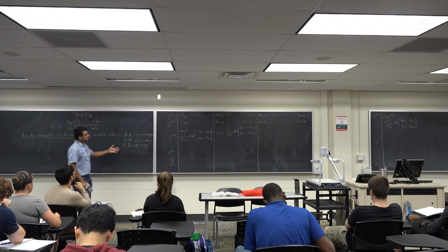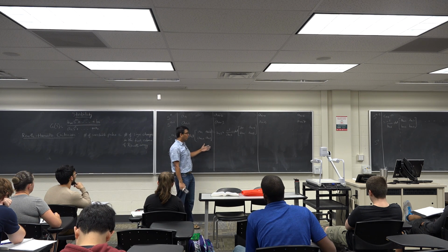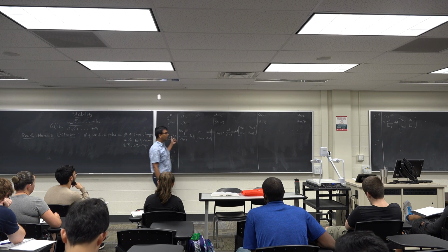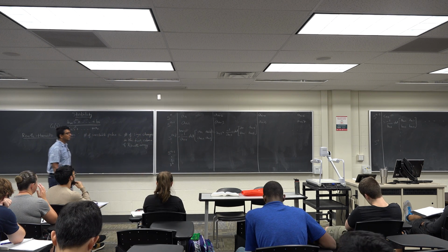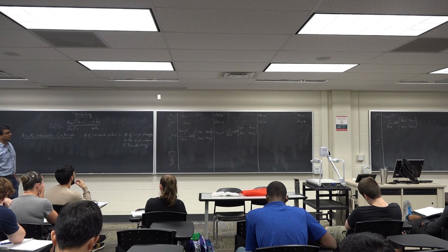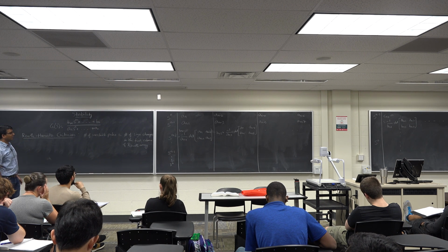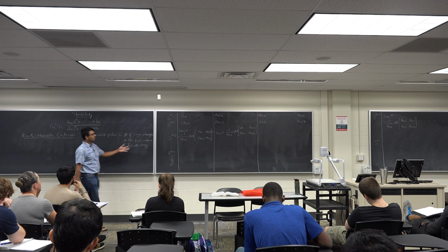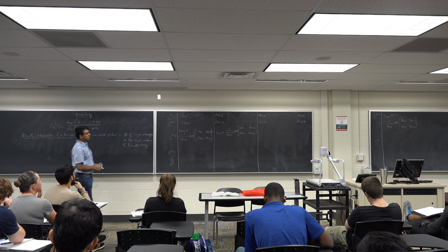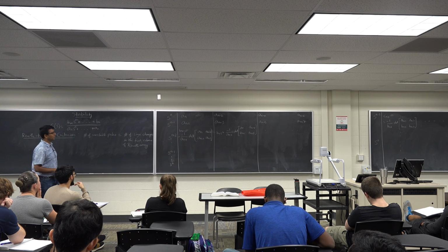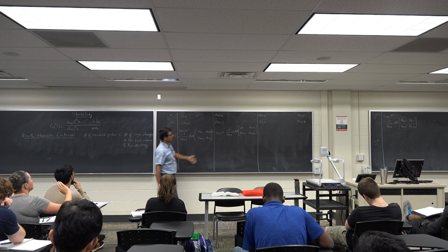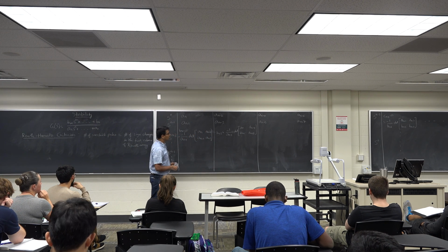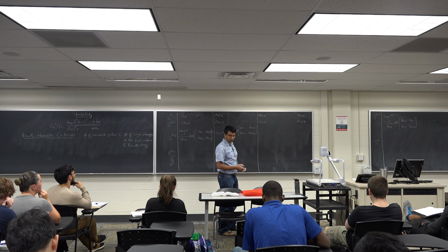So constructing this array is not a problematic affair even in the 1870s. If you know the system's transfer function, you can construct this table. It's still a laborious task, but it can be done by hand. And you can ascertain how many unstable poles are in the system just based on this criterion: look at the number of sign changes in the first column of the Routh array. Let's try to do it for a very simple system because we don't have much time.